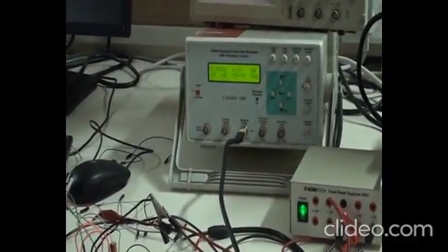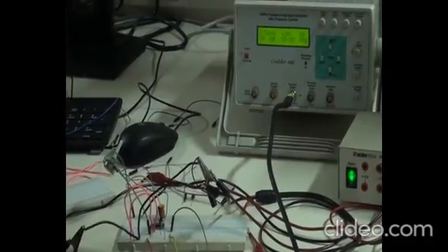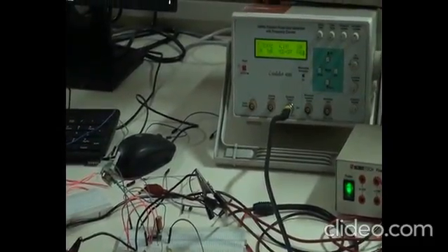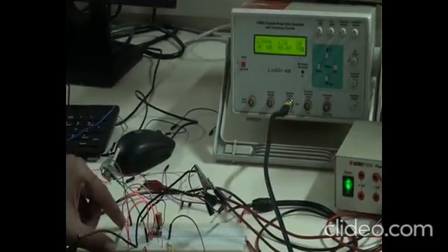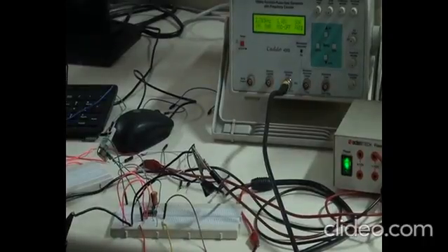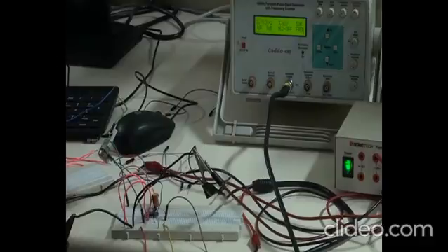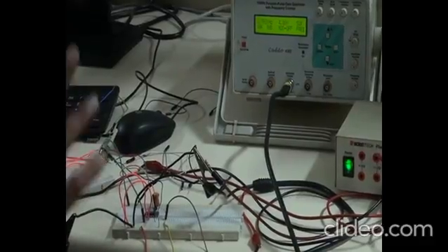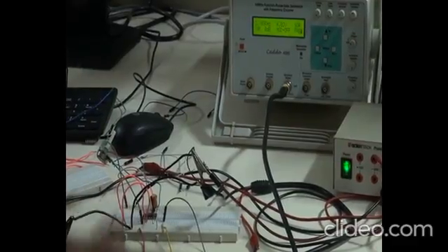And pin number 8 you have connected a 270 ohm resistor to VCC. Pin number 9 you connect to minus VCC. That's again to pin number 1 or to the top line that you have connected. And pin number 10 you connect to plus VCC, and that is plus 5 volt. So this particular IC you are using both plus VCC and minus VCC, that is plus 5 volt and minus 5 volt. And the output you are taking from pin number 4.